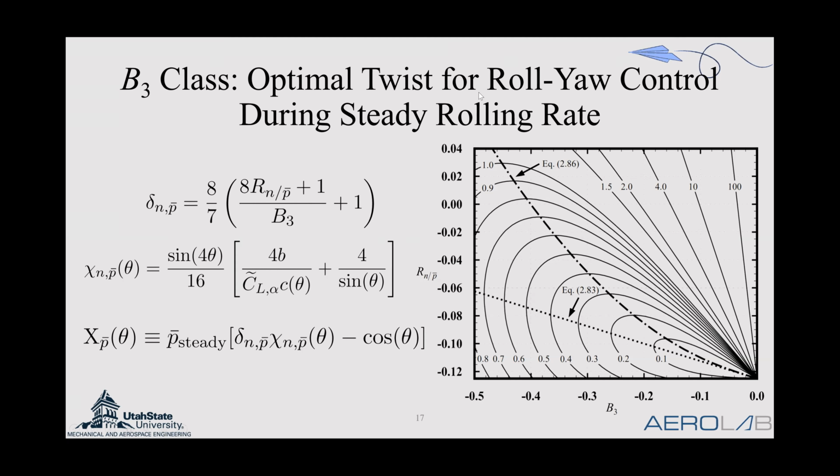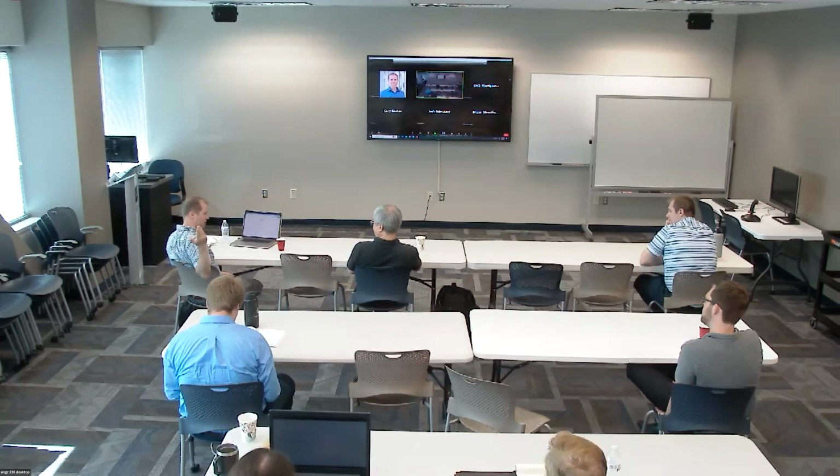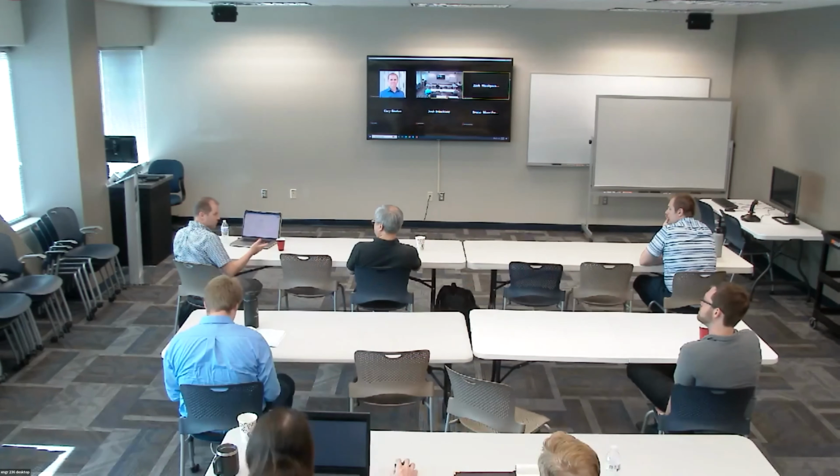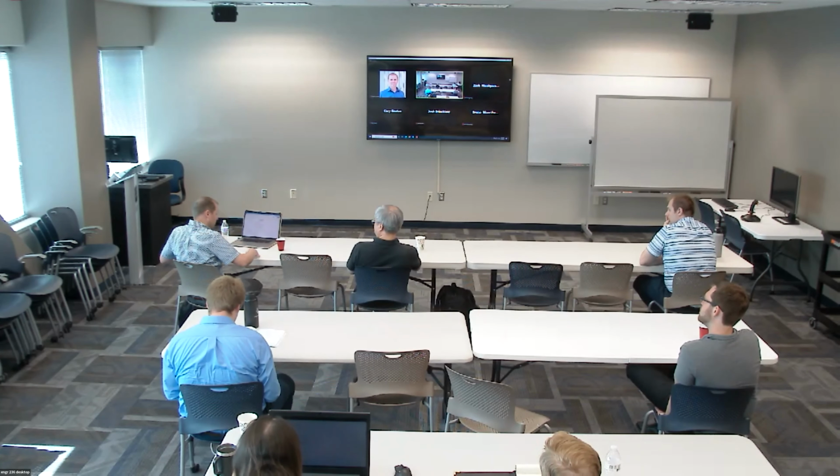So what we do right now on the Spitfire or any aircraft, basically they mix in the rudder to cancel out the adverse yaw. But that was the point of Al Bauer's work. He said, look, if we have a bell-shaped lift distribution, we can deflect these ailerons and it will actually give us proverse yaw. So we don't need a rudder to counteract the adverse yaw. And so when we bank right, the aircraft will also yaw right. Or you can also design them so you get zero adverse yaw, meaning the aircraft doesn't yaw at all.